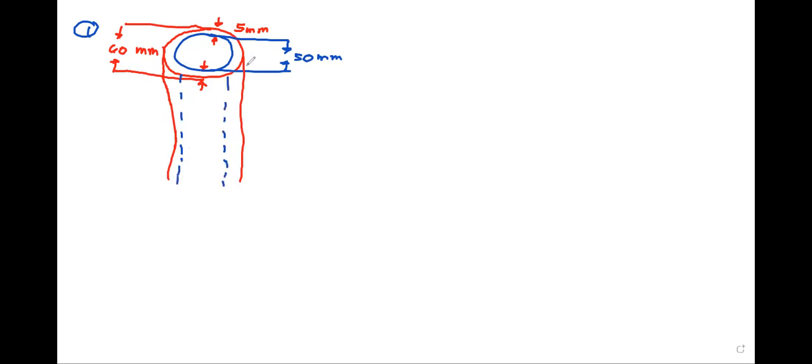They have a length, and since it is constant, they are the same, with a total length of 2 meters. Let's convert it to 2,000 millimeters for the sake of consistency. Next, what we are looking for is the applied load. Let's say P is the applied load. So, find the applied load. The problem also says to compute the load that will compress the combined bar a total of 0.8 mm.